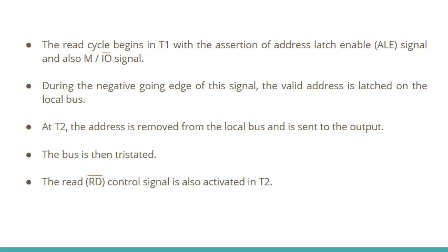The address bus status lines will indicate the status values, that is from S7 to S3, after the T1 clock cycle. The status lines will be available on these address bus status lines. And in the address bus data lines, from the T2 clock cycle, they will be used for data, that is the time multiplexed address bus data lines will be used for receiving the data after the T1 clock cycle and during the remaining clock cycles.